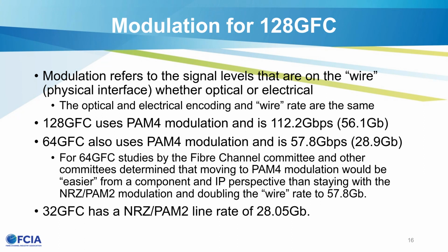And I think it's important to see the distinction here because 2 levels of backward compatibility is always key. In the standard, the framing and signaling standard, they specify 4 levels of backward data rates of backward compatibility, but with the modules, usually there's the primary rate and 2 rates back. So it is important to understand, if you buy a 128 module, you would expect it to be able to speed negotiate to 64 and 32 also.